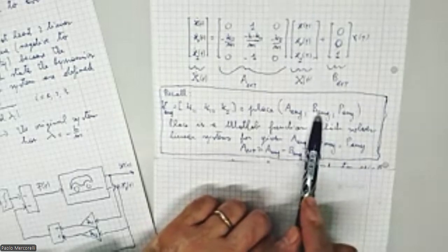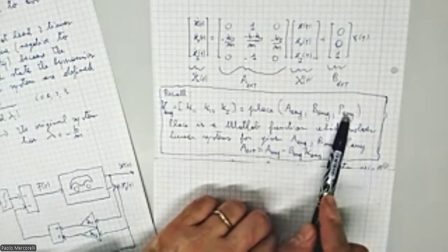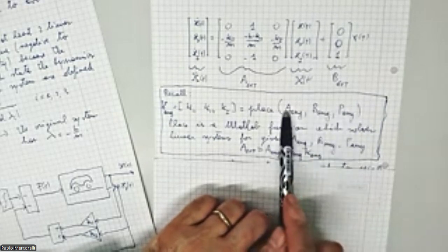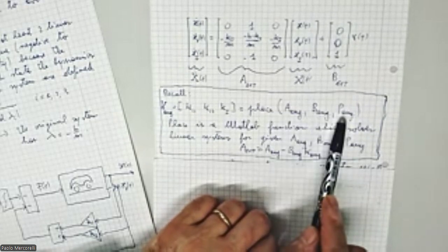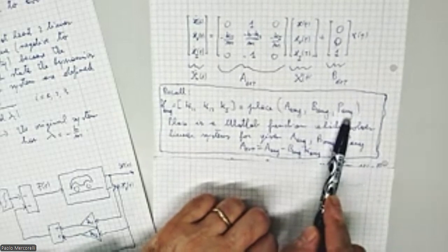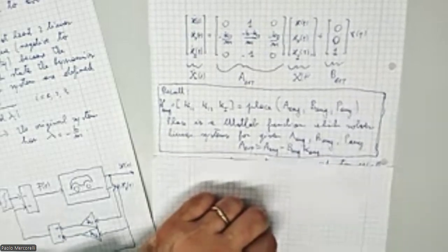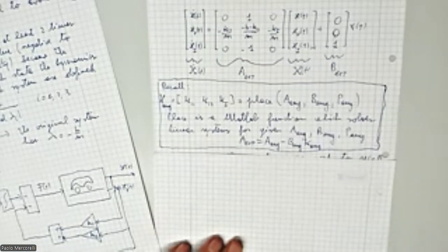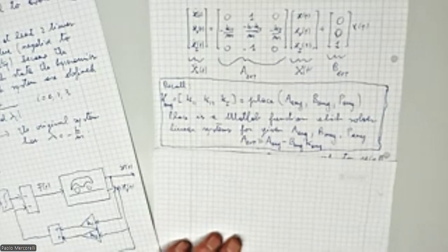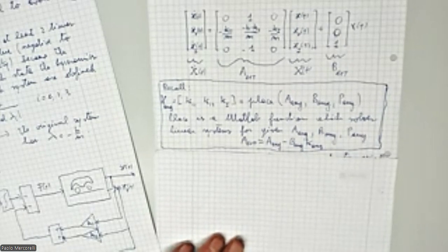And here is a vector P: this is a matrix, this is a vector, this is a vector. We will consider the desired, or better to say the requested, eigenvalues, which reflect what we want to attain practically. We don't want, for instance, to have oscillations. This means the eigenvalues should not include an imaginary part. About that, I will tell you in a few minutes. Now, look.